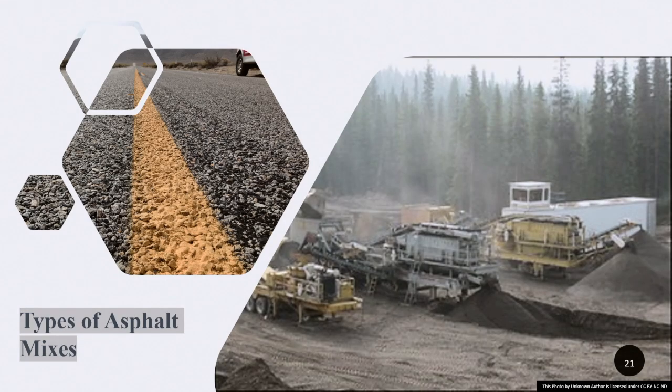Now coming to the types of asphalt mixes, I guess it's pretty standard. The only differences is how to proportion our mixes, whether we are using Hveem or using Marshall or using Superpave, or now after Superpave we implement the balanced mix design. These are all developments when it comes to proportioning our asphalt mix or fabricating the samples to be tested.